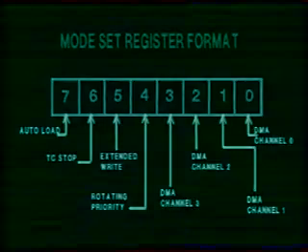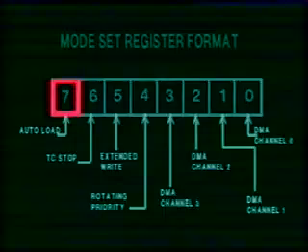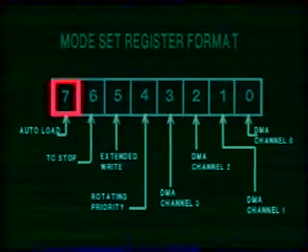The highest bit in the mode register, D7, enables what is called an auto load operation. This auto load function is available only for channel 2.